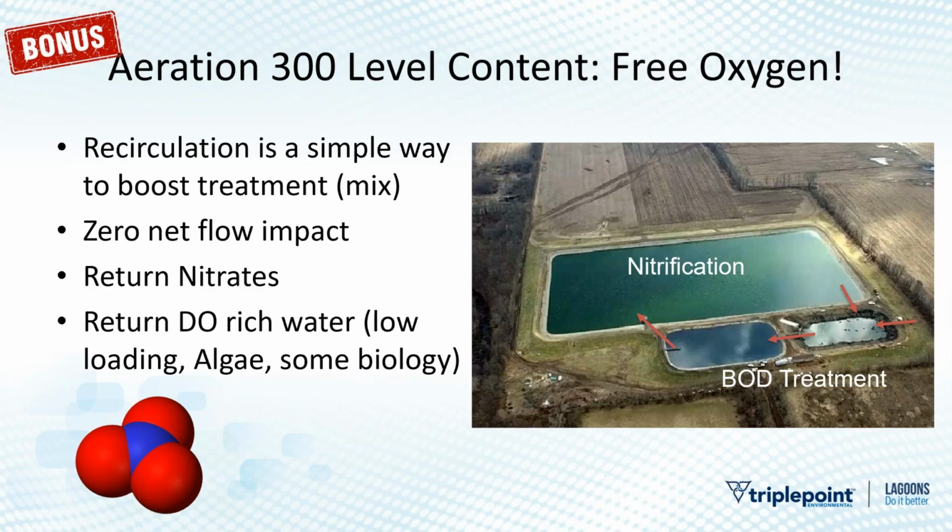And what happens is these BOD bacteria, these heterotrophs, will actually go to this when they don't have enough air. They will rip off the oxygen molecules, and the nitrogen will just off gas. So essentially, this nitrate brings a lot of value in oxygen into the cell, and these bacteria know how to use it. The other benefit is this cell has low BOD and has a lot of surface area.